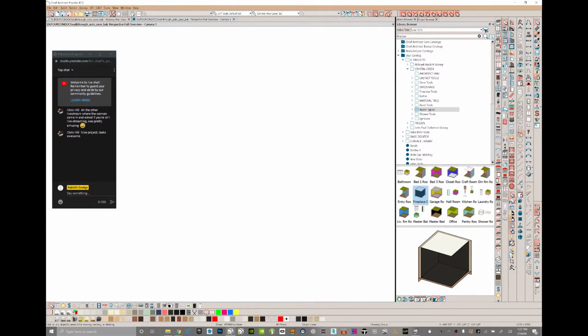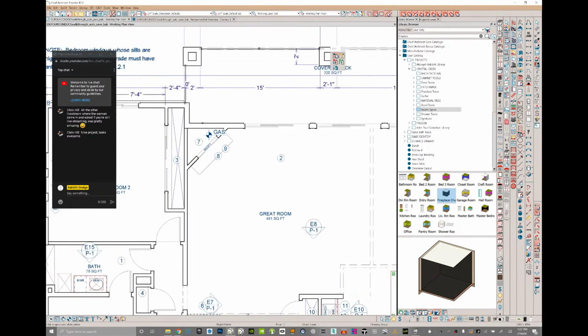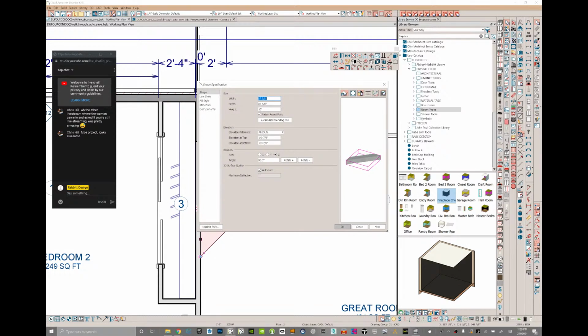And let's just get back into plan view and I will fix this mantle. I have a mantle tool using a hearth. I have a hearth tool using a cabinet, but cabinets don't like angles, so we're just going to stick with this P solid. And so probably what I'm going to do is shrink this down. The height, we're going to drop an inch and a half off of this.